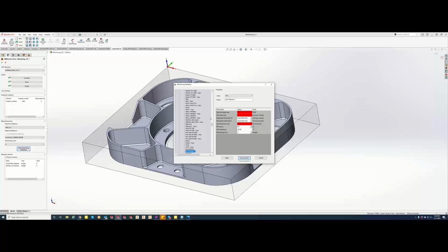There are just 3 parameters that we need from you to utilize the iMachining algorithm. This is going to be the same for 2D iMachining or 3D iMachining. This is something that you do not need to create every time. Once you've created it, it's in your iDatabase forever, and you won't have to worry about it. For those of you new to iMachining, come in here, give it a machine name, max RPM, max feed rate, as well as horsepower. Those are the 3 key variables that we're looking for.